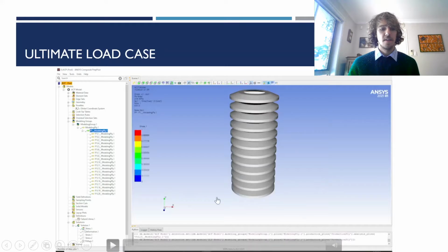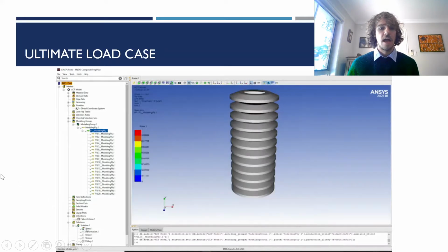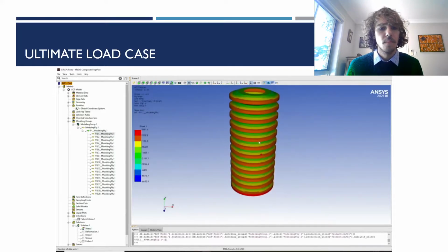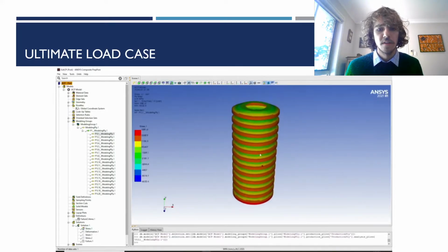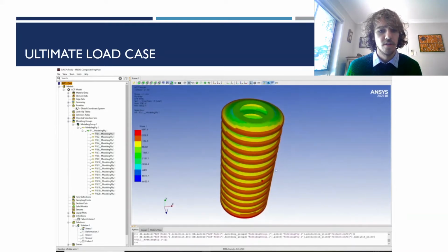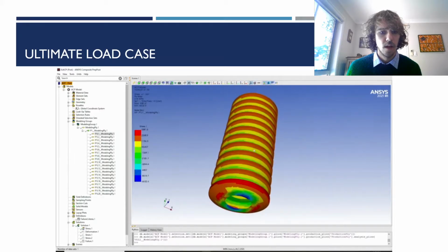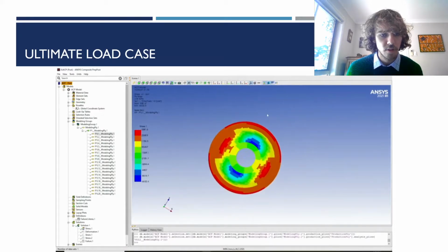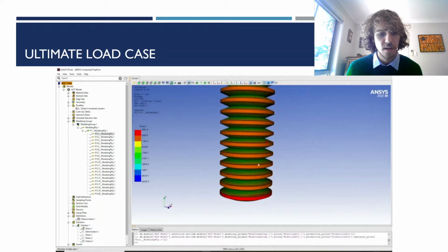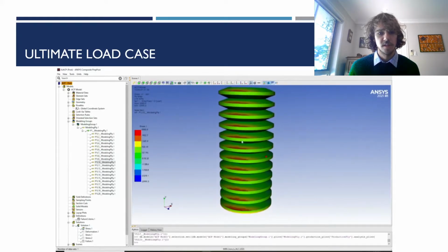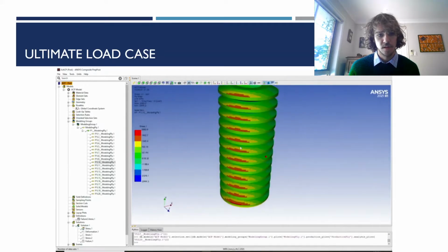So we can see here that analyzing it ply by ply, we can see the stress concentrated regions in each laminate. So the stress is here, and this also shows you that using just a typical shell element is not as accurate as using the ACP post-processing tool, because the stress values are quite different.